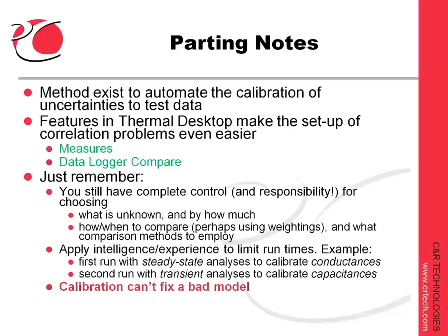Hopefully, you have enough test data to exercise that model under enough conditions that the calibrated model can be trusted, because there's always a test you can't perform or can't afford to perform. Otherwise, we wouldn't be doing a thermal fluid model in the first place.